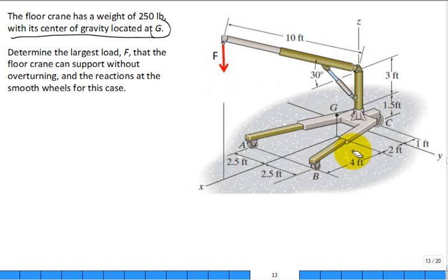That's right, your center of gravity can be in the air, kind of like if I had a pipe like this, it was bent, right? And I said, where's the center of gravity of that pipe? It'd probably be around there. It's in the air, not on the pipe. But this is the same thing here, the center of gravity right there, G.